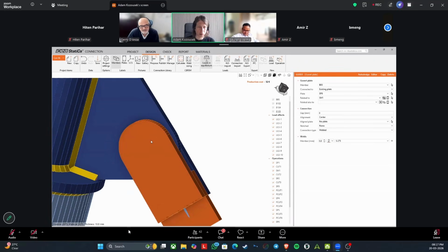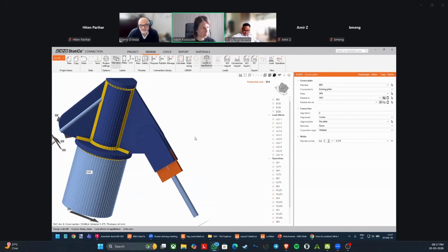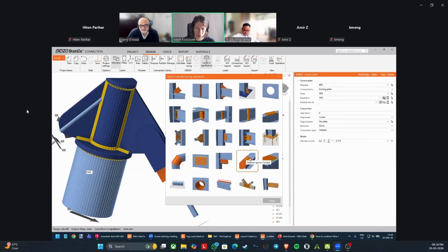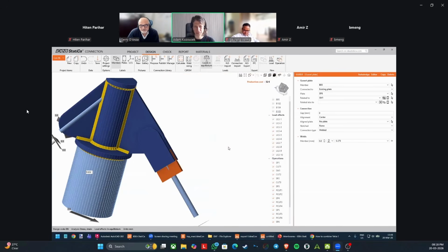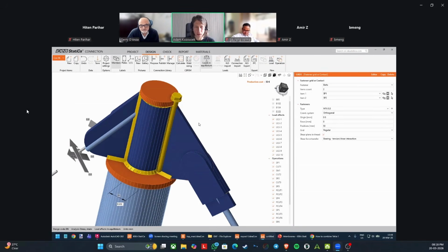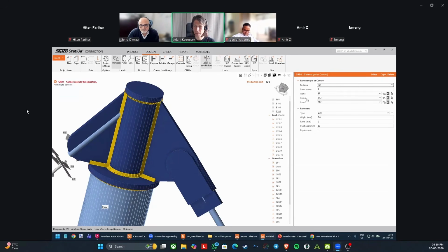And the last thing here I want to do is to create the pin. Right, so let's go to operations again. And here I choose the fastener grid or contact. Okay. So you can see there is some bolt in space, and I will change from bolts to, I have this menu, I can choose anchors, pin or contact. So obviously I go for a pin.